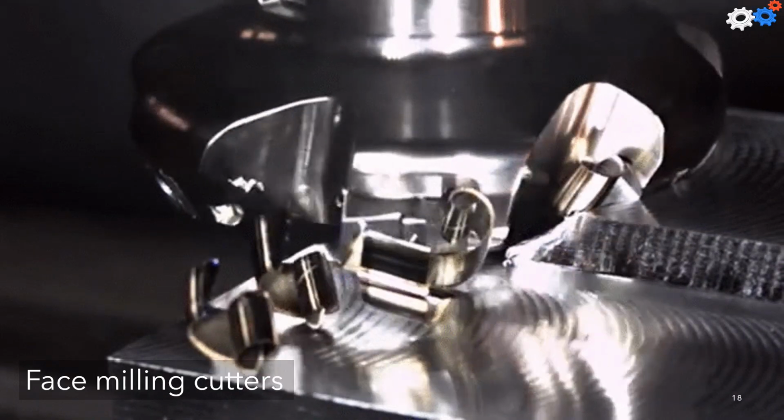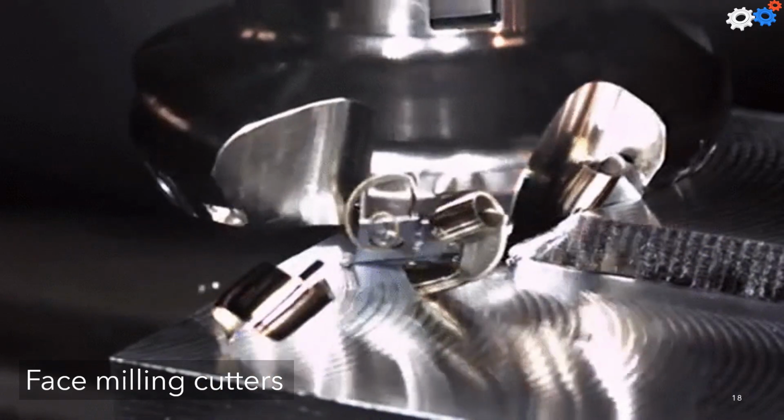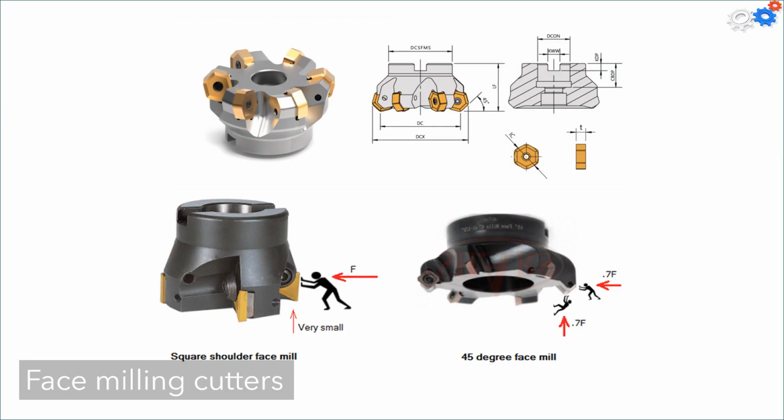The face milling cutters are designed with teeth that cut on both the periphery as well as the end of the cutter. The face milling cutters can be made of high-speed steel, and can be designed to use cemented carbide inserts.